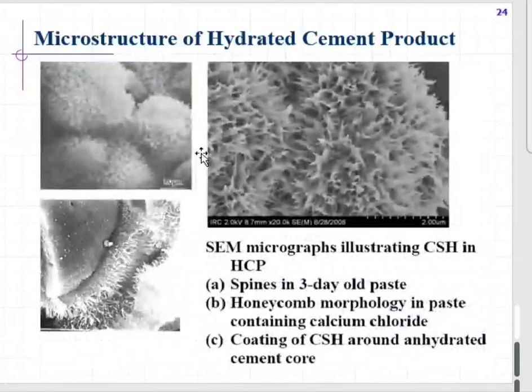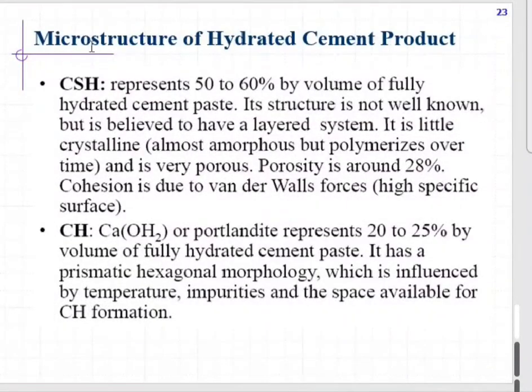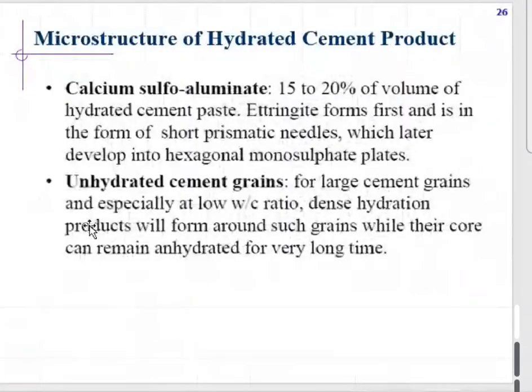So if we see that over here, maximum we want from the cement is the C3S-CSH. This CSH, or calcium silicate hydrate, will give us the most stable structure for the cement paste, to get the main strength and more durability. However, we have unstable CH, which will lead towards instability or durability-related issues. I hope you have studied it in your durability course, but if not, we'll discuss it inshallah.